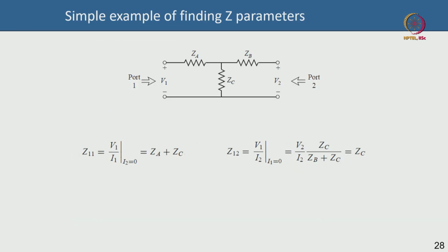Now just to give an example or a flavor, I talked about Z parameter, Y parameter, S parameter. Although you measure S parameter, if you want to practically gain insight about, say, cutoff frequency, then you cannot just use S parameter, you have to convert from one to another. So, it is not like Z parameters and Y parameters are meaningless, they are very much meaningful.